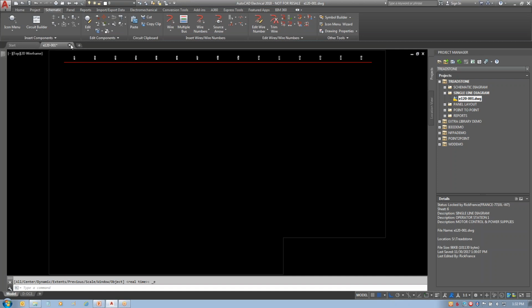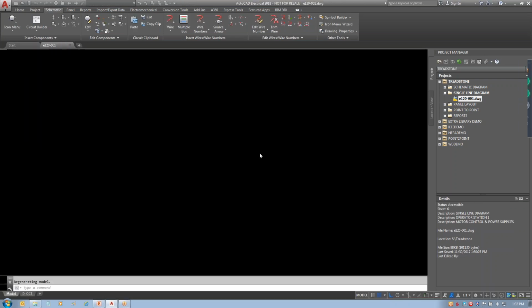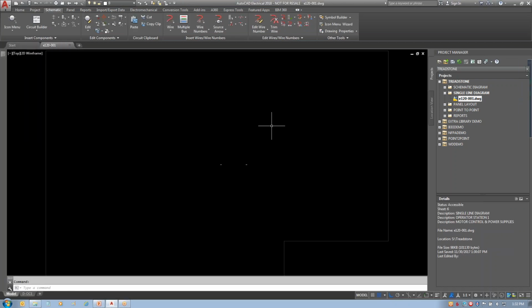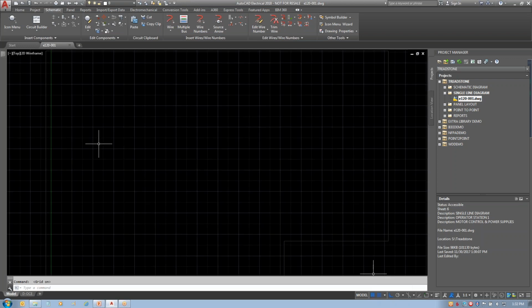I don't want to do that because since I am planning on using it as an interactive drawing, I'm going to go ahead and use it by just drawing a wire. Now, before I draw the wire, I'm going to use my grid, which I also have set up in the template. Basically, it's set up along with the snap to do a 1-inch grid with 2-inch major lines. Makes it a little bit easier for me to make sure everything's nice and even across this when I draw it. And I'll draw it by adding a wire here in just a second.